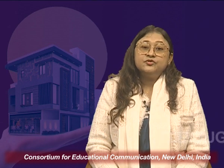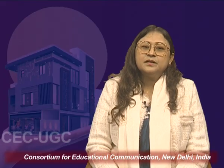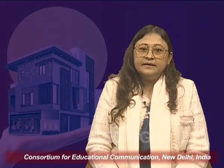The balcony projections are not calculated in plinth area. The curvature or any design improvements which don't have any functional value will not be calculated in plinth area. Platform without cover, terrace or the floor above will not be calculated in plinth area. Any dome, terrace tower or spiral staircase will not be calculated in the plinth area.